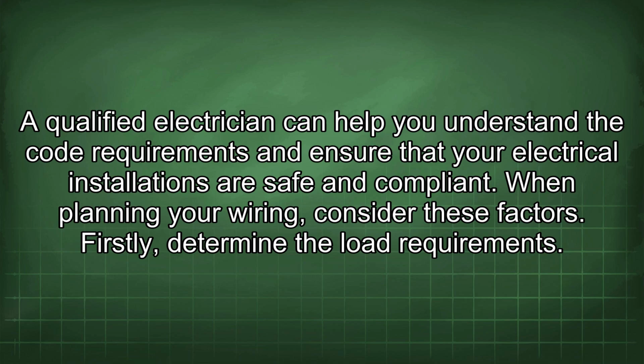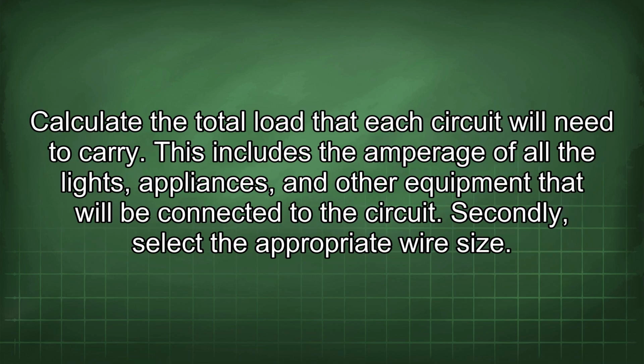When planning your wiring, consider these factors. Firstly, determine the load requirements. Calculate the total load that each circuit will need to carry. This includes the amperage of all the lights, appliances, and other equipment that will be connected to the circuit.